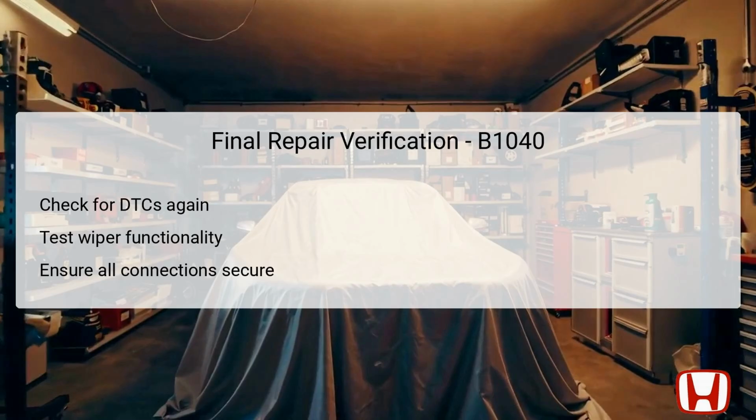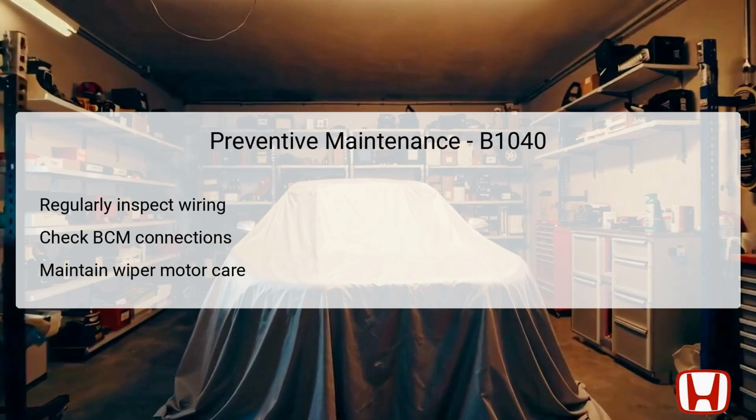Next, test the functionality of the front wipers to ensure they operate correctly in response to controls. Lastly, confirm that all connections associated with the wiper system are secure, which helps prevent any future communication problems from cropping up. To prevent the recurrence of DTC B1040 in the future, implementing a routine maintenance schedule is essential. Regularly inspect the wiring associated with the windshield wiper system, looking for frays or any signs of wear and tear, which can lead to communication issues.